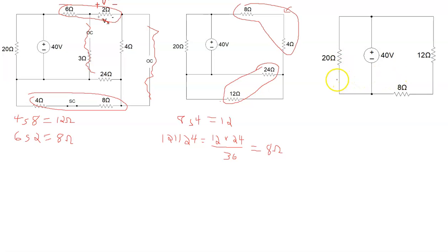Now over here we are trying to find a current that goes this way, so let's think about our original circuit. From the source, the current that goes this way is this current here, and because there's no connection here, that current also goes through the 2 ohm and comes over here and goes down through the 4 ohm. In fact, there's only a series branch that current goes through before it divides here. So we don't need to include this 20 ohm in the calculation.